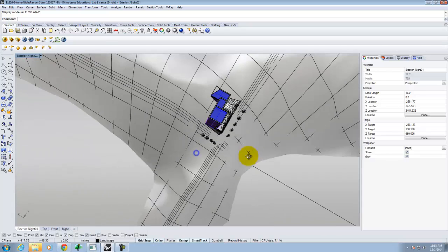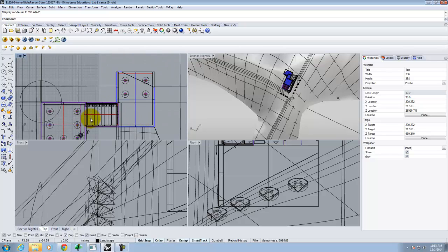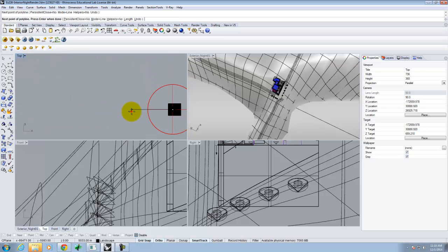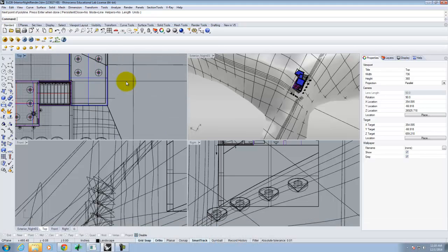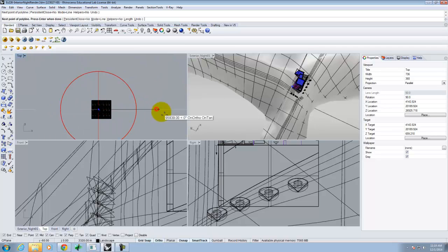So what I'm going to do is switch into my top view so that I can see what I'm working through here. And I'd really like to cut the section right through there. That would be ideal. So I'm going to start with just a plain polyline. I'm going to turn all of my snaps off for right now. And I'm going to draw that polyline through, starting in one part where I want to cut my section. And so I'm just going to go way out big. There's one side of it. All right, let me zoom back in. And I'm doing this in the top view with a line like this. We'll turn the snap back on so that it's really easy to get it larger than that giant circle out on either side.